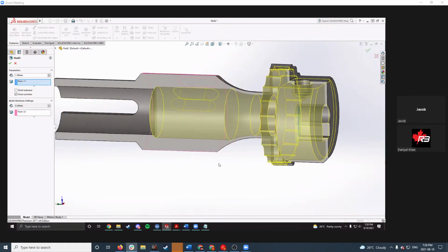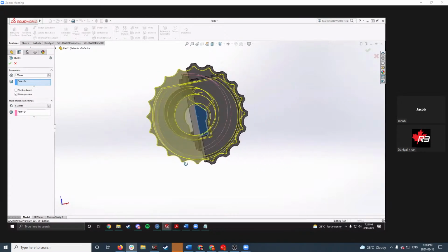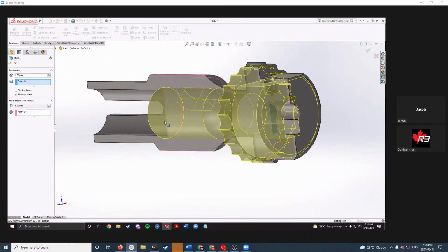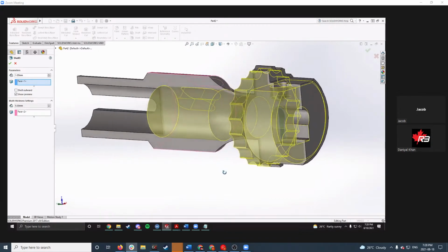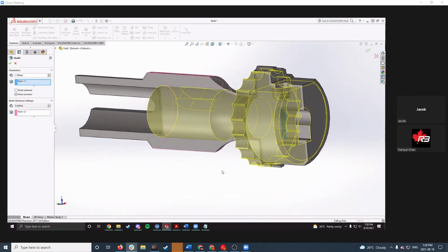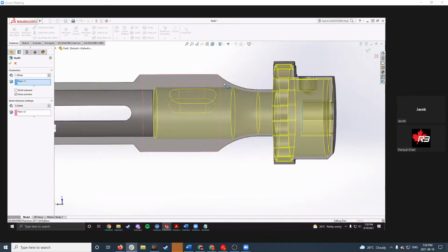here at the top, it notices that since you have that shell 5 millimeters away from the outer edge wall, that shell would interfere and act weirdly with the top face, or the bottom face, of that cutout from the top side.